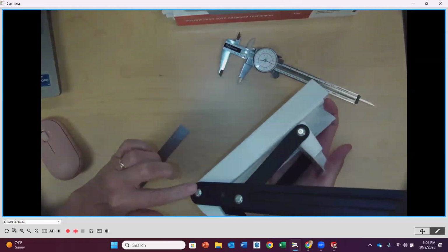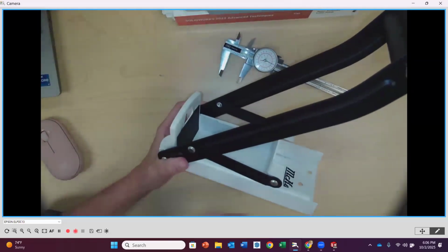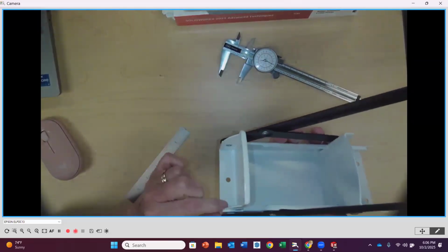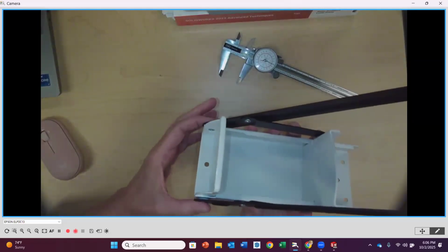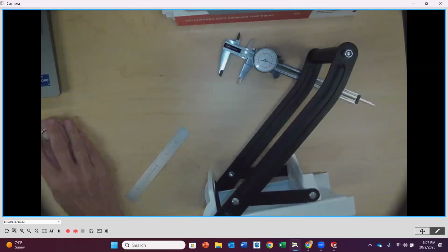Lastly, before we look at form tool, there are rivets holding the arms in place for each one of these features. So there's 1, 2, 3, 4, I call them short rivets, and 2 longer rivets because this is sandwiching a little bit more material together. So you've got to have a little bit longer rivet on the 2 on the bottom. Now, as far as rivets, there are none in the toolbox, so you have to create them, or model them. Very simple. I'll show you what I did.